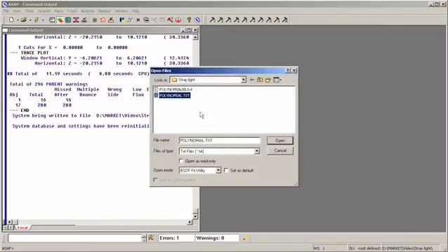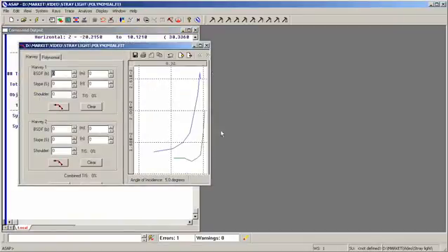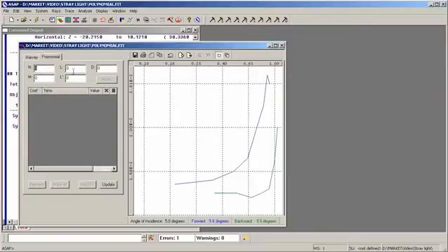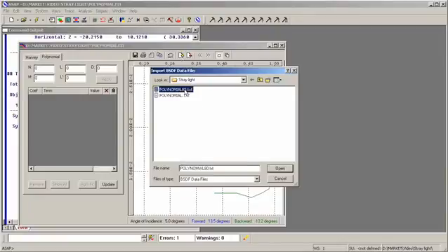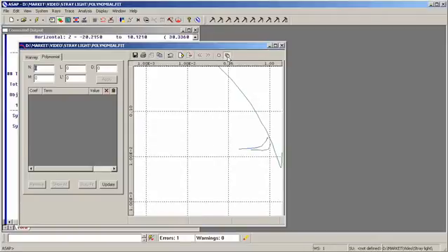All right, we're going to open up this file in our BRDF fitting utility. Here it is. This shows our measured data in the forward and backward scatter directions. We'd like to fit this to a polynomial model, so we'll pick the polynomial tab. This is 5 degrees angle of incidence. We also want to bring in the 80 degrees angle of incidence data. So polynomial 80, bringing in, and we want to display them on the same graph, so we simply click on this multiple page button. So here's our 5 degree data, and here's our 80 degree data.